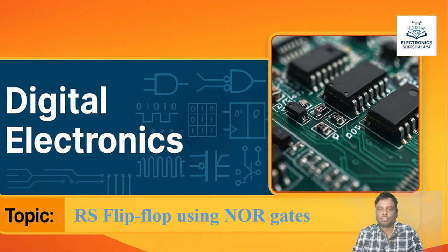We have seen that flip-flops can be constructed using three sections. One section is an edge detector circuit. The second section is the steering gates. The third section is the latches. Basically, flip-flops are constructed using latches, and here we are using the NOR gate as a latch. Let us see how the circuit operates with different combinations of inputs, that is R and S. So let us get into our discussion.